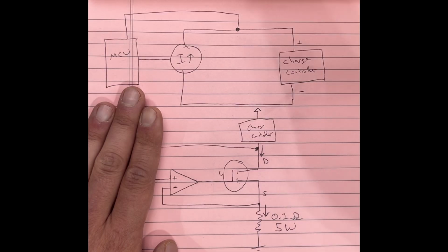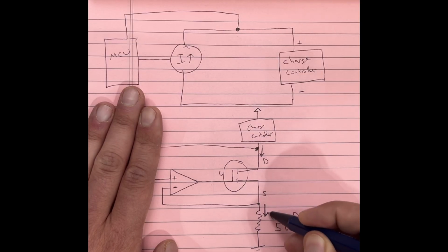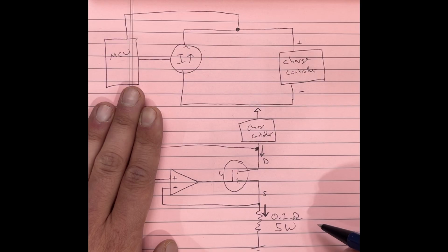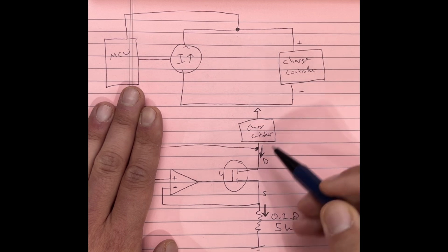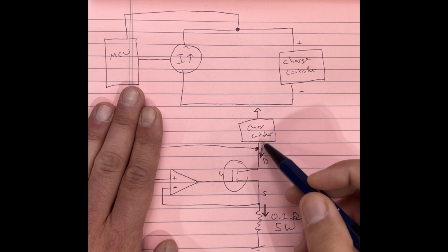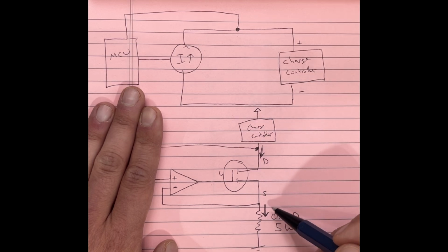And so every voltage source is also a current source. If I can set the voltage across this resistor, then that means I'm also setting the current across the resistor. So the current being driven through here is a known value based off the voltage. And then, this MOSFET, the current flowing into the drain is about the current flowing out the source.